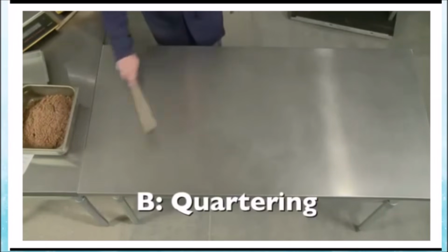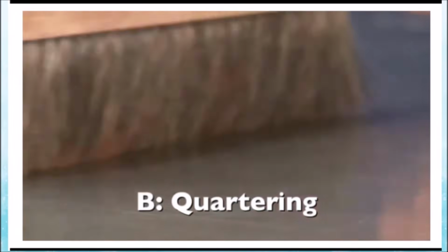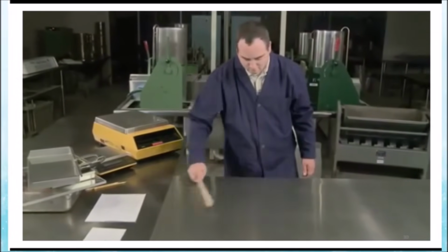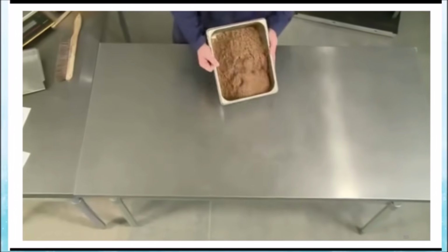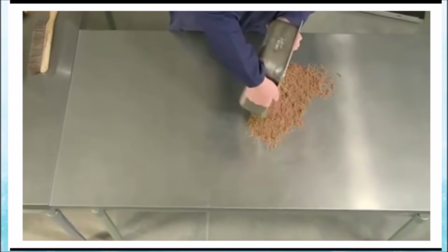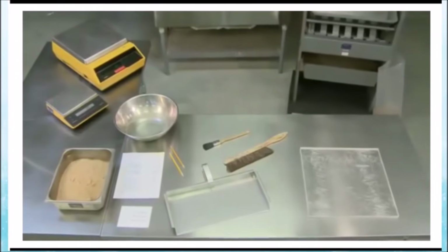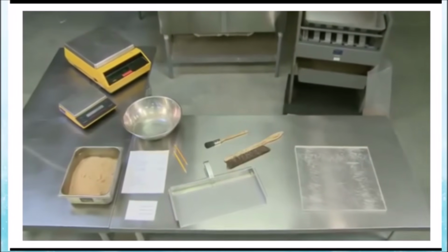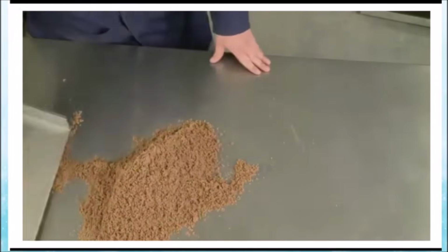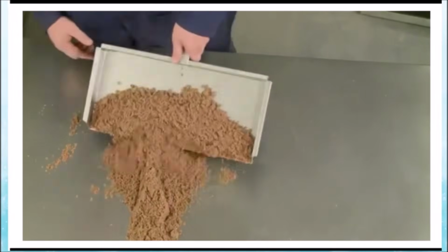Method B employs the use of a hard, clean, level surface or a canvas blanket. It's always a good idea to brush the surface before you begin. Place the sample on a hard, clean, level surface that will not contaminate the sample. Brush or wipe clean all utensils that will be used during the procedure. To ensure the material is thoroughly mixed, the entire sample must be turned over a minimum of 3 times.